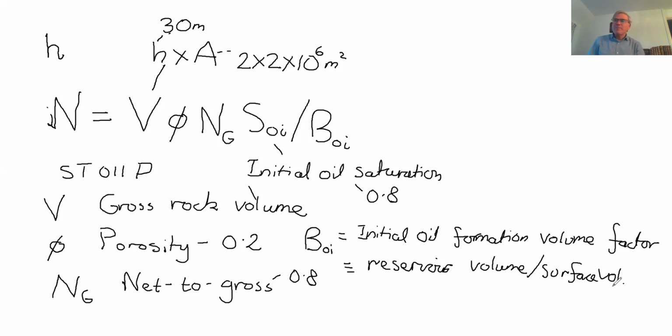That actually is incorrect. BO is typically going to be greater than 1. It's greater than 1, and a typical value I'm going to put in here is, say, 1.6 for quite a light oil. So how can oil shrink when you drop pressure? It's because of what was described in one of the former slides, but very quickly: oil is a mixture of hundreds of different chemical components. At high pressure, light components that would be gases at surface conditions can dissolve in the oil. So often the principal components chemically are going to be methane, ethane, maybe even CO2.